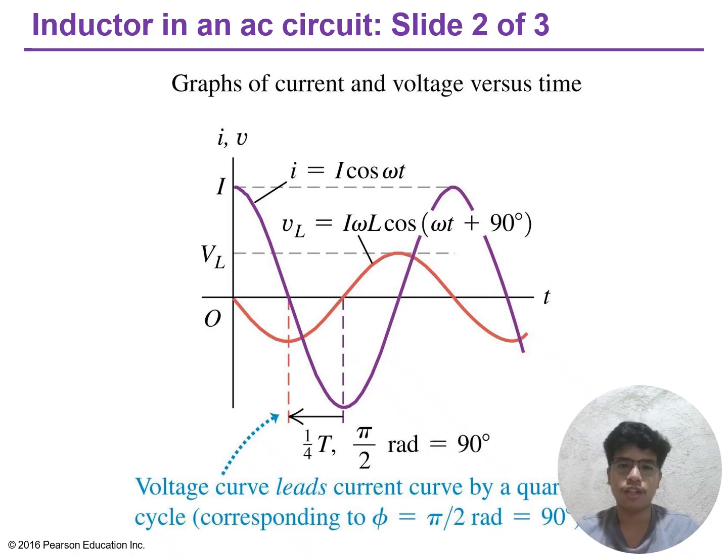Mathematically, if the voltage is expressed as v(t) equals capital V times cosine of omega t, then the current is i(t) equals capital I times cosine of omega t minus pi over 2, or equivalently capital I times sine of omega t. So this 90 degree phase shift is caused by the inductor's property of self-inductance. The induced voltage opposes changes in current, creating an inherent delay between the applied voltage and resulting current.